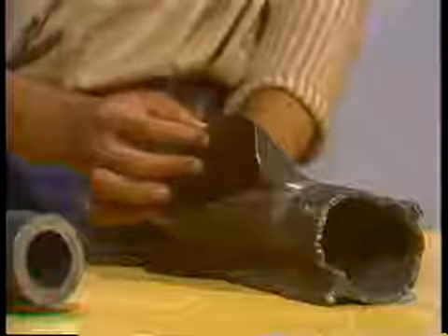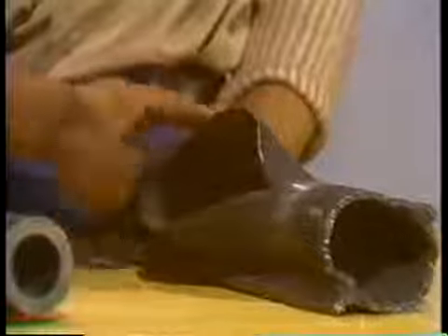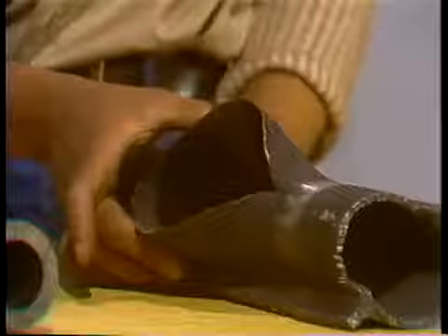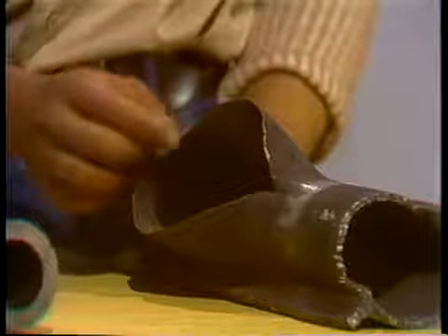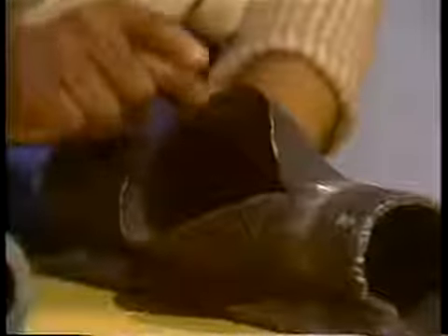Thin-lipped ruptures are usually caused by sudden and severe overheating. They look something like a burst bubble. The open lips are uniformly tapered to sharp, knife-like edges. There is no evidence of cracking or irregular tearing of the metal in a thin-lipped rupture.